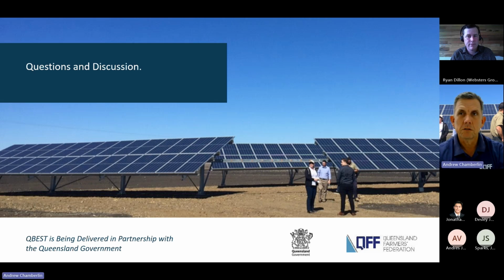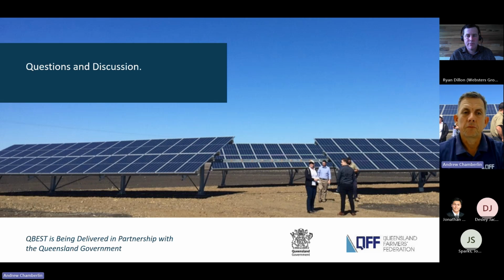But also just wanted to say how relevant that is, and perhaps you could comment, Ryan, to people that do have solar systems, when the solar system might start to slow down its generation in the late afternoon, so that if people do have good cold rooms that have good seals and are able to keep the doors closed in those evenings, the cold room condensers and fan units might actually slow down in that evening period and use less power in a good quality cold room.